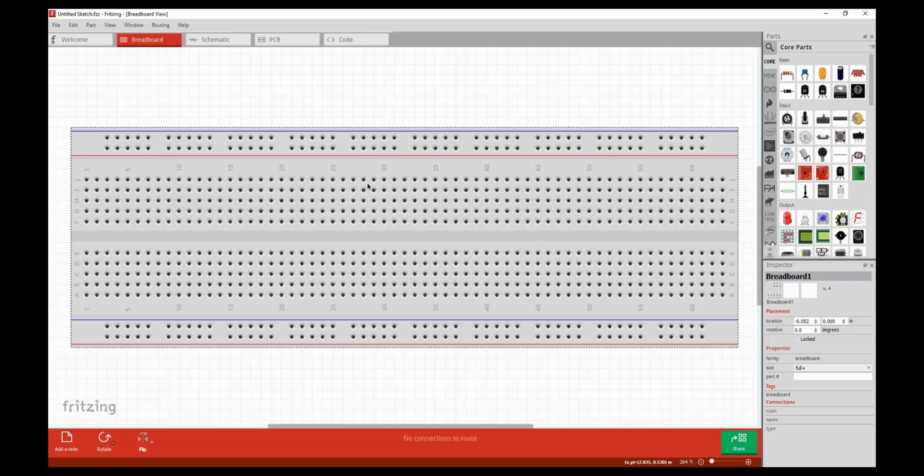In the lecture that I've shared earlier regarding familiarization with function generators, DSO, and breadboards, you already are familiar with how the connections on a breadboard are made. Like these 5 holes, each of these 5 holes are connected to each other. That means you can have a node having 5 different branches. Each of these could be a node having 5 different branches. This entire row is connected to each other. This entire row is connected to each other.